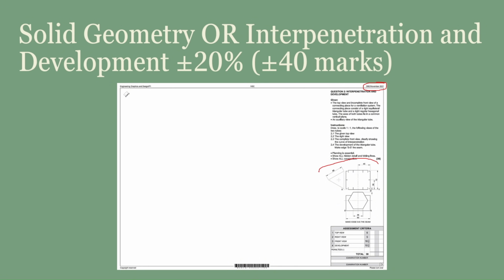We also know that the first paper is drawn in first orthographic angle. So this will be our front view and this will be our top view. Some important tips that you can take with you. Number, very important. When you number your corners, it is easy to project them to the secondary views to get marks of the specific corner. This allows you to understand and see the view better in that view.